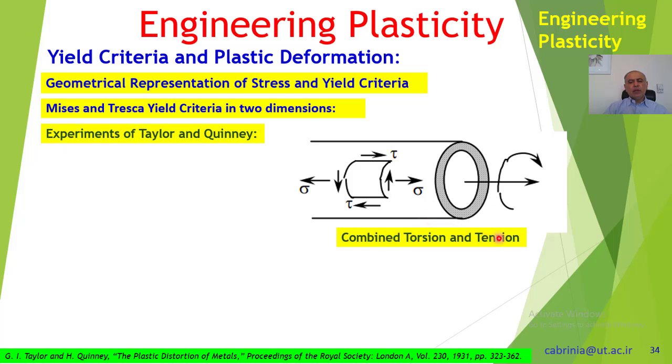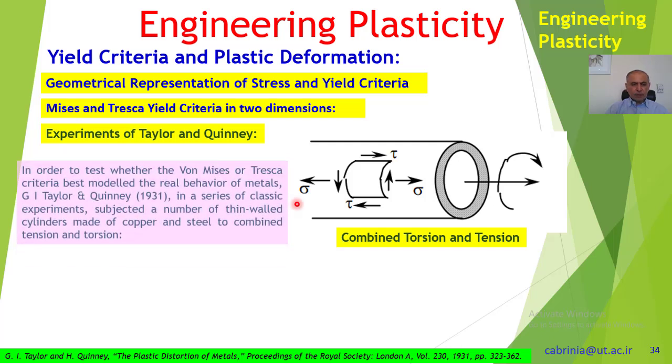So why do we put it under combined loading? Because we want to have shear and normal stresses and stresses applied in all directions. Okay, so that's why we put these combined stresses. As I said, we could put internal pressure and bending, internal pressure and torsion, compression and torsion, compression and bending, all sorts of combined loading we could apply and get the results. What results do we get?